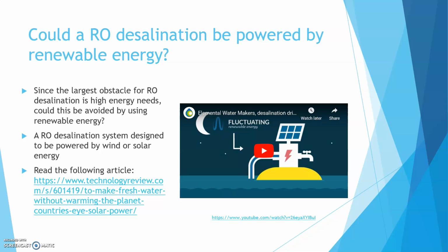It is capable of removing up to 90% of dissolved salts, particularly salt content ions, particles, colloids, organics, bacteria, and pathogens from the feed water. An RO membrane rejects contaminants based on their size and charge. Any contaminant that has a molecular weight greater than 200 is likely rejected by a properly running RO system. Likewise, the greater the ion charge of the contaminant, the more likely it will be unable to pass through the RO membrane. For example, a sodium ion has only one charge, that is monovalent, and is not rejected as well as calcium, for example, which has two charges.